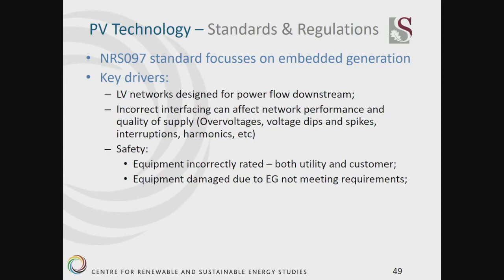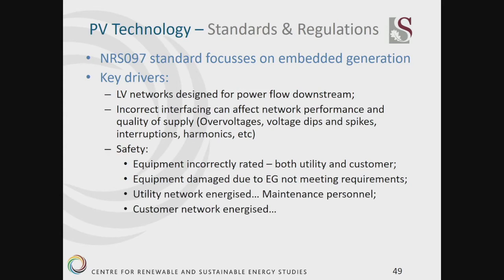and if you don't comply with the technical standards, you might also put the network at risk, and this has other safety implications. So a customer can't energize the network while the network is down. So this basically means when there's a blackout or load shedding, you must not be able to feed energy back into the grid.